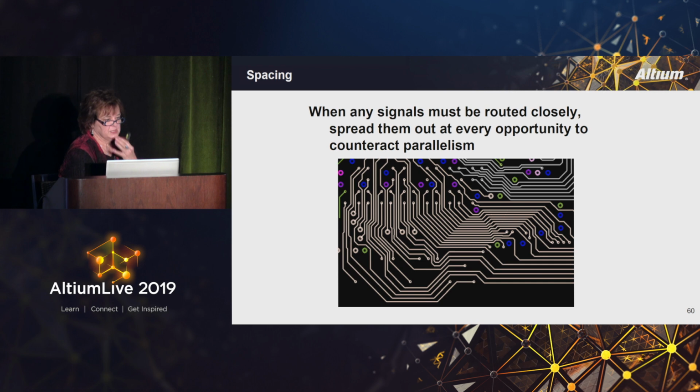If you have any kind of buses that are going through your board, it's a good idea to spread them out every so often, because to route them in this kind of a manner from point A to point B is acceptable, except that if there's any extra energy that happens to get picked up by anything, it can all spread to all of those other traces. So if you have the opportunity to spread them out, I would spread them out even more than this picture would show, down into this where I could get all of these spread out down here and then go off a little farther. They may have to come back together and go back out and come back together, but you're giving them the opportunity to lose that coupling with the other signals, which is what you want.